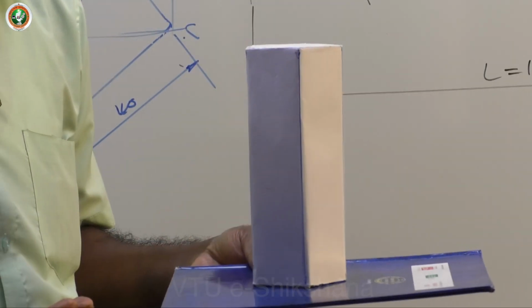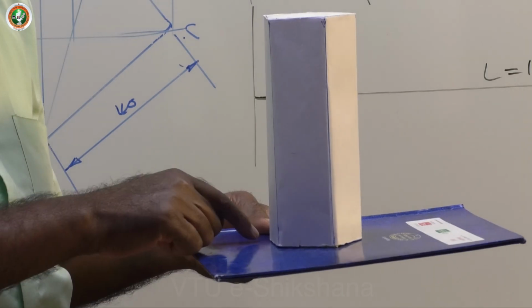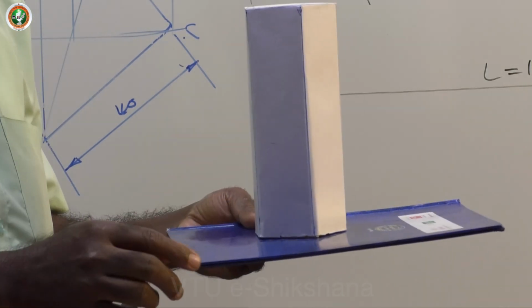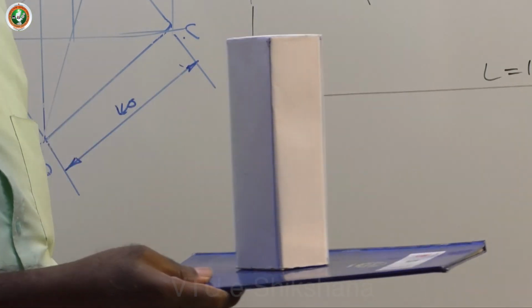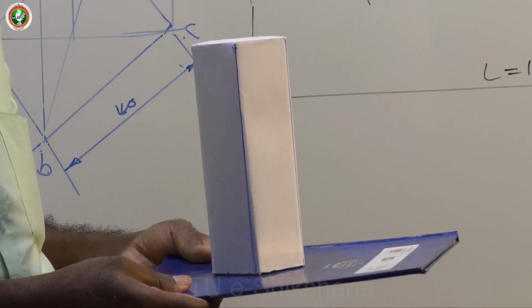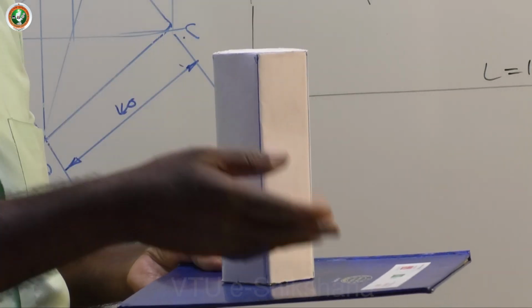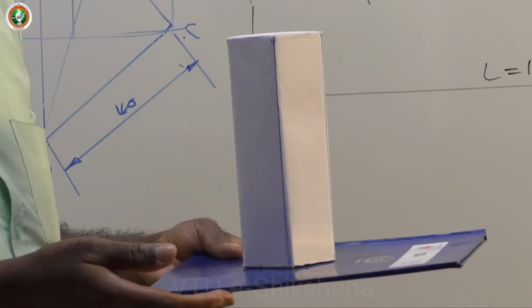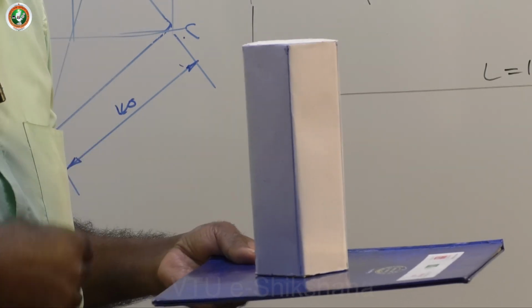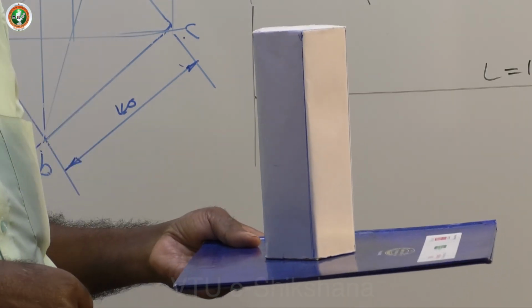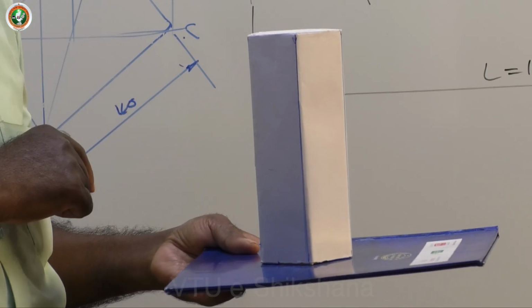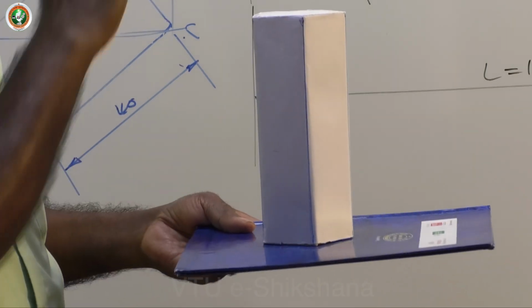Then you will give cutting section plane. Now this particular edge is perpendicular to VP. So you can ask me, why not you take to the right side? Yes, definitely you can take to the right side. Normally by default we will take to the left side and start working. Now this particular orientation works for the given problem.